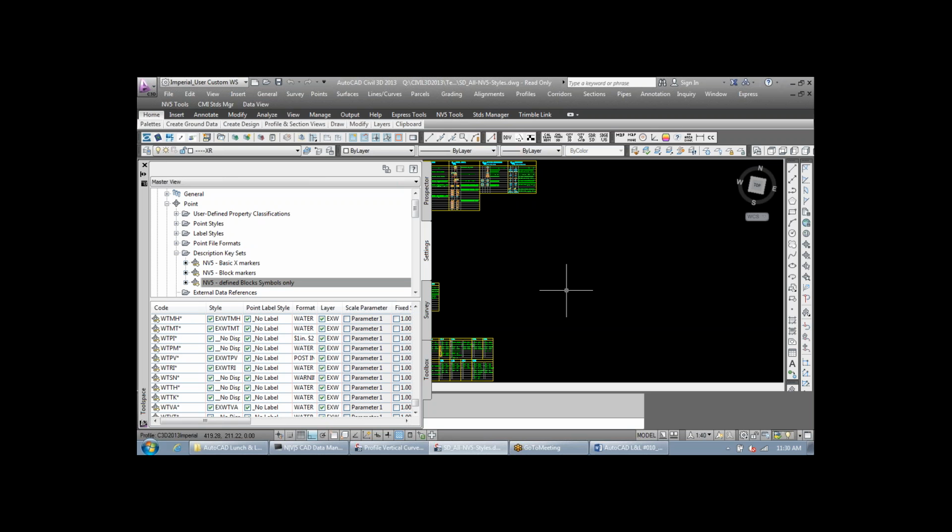Even if you're using an older file, it may not have the right style set up in your drawing. Even though it's set up in your survey figure in the survey database, it needs to be set and matching in both the survey database settings and your drawing file. So all those should be set. If you experience anything, please let me know so I can correct it.